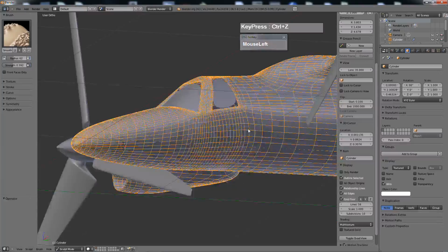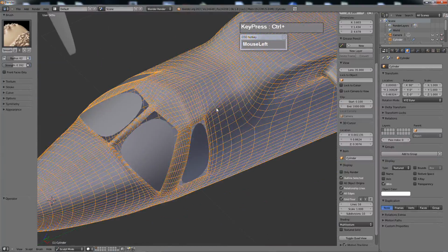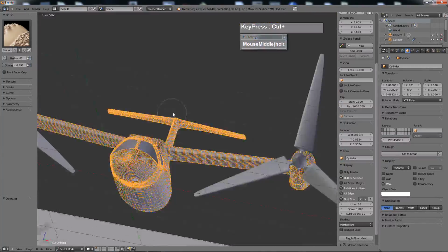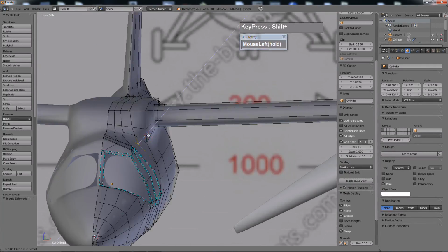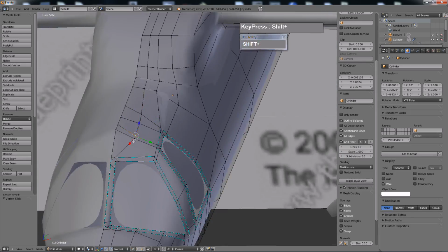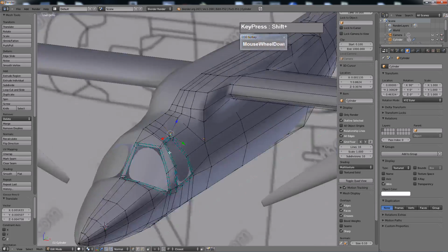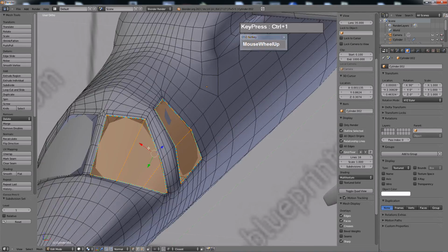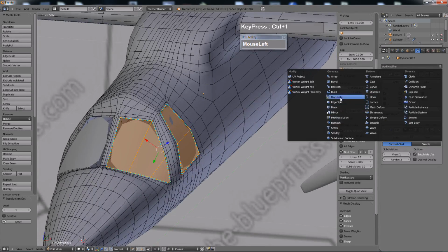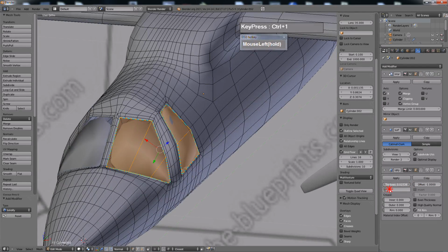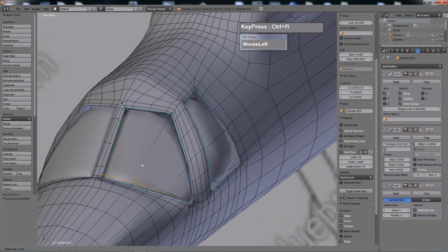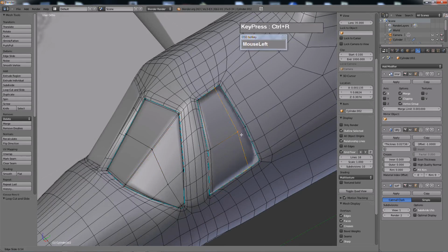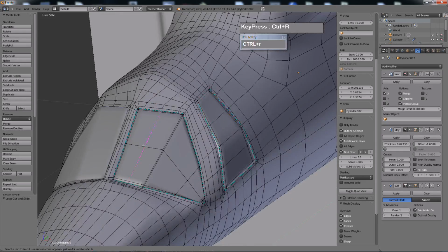And right now I'm using the sculpt tools to help me smooth out problem areas. So the sculpt tool is not only good for doing sculpting, you can use it to smooth out areas which you want to have a nice smoother surface. But in the end, you might still have to take the vertex one by one and manually move it. So while it is still at a relatively low vertex, low polygon stage, it is generally much easier to edit.